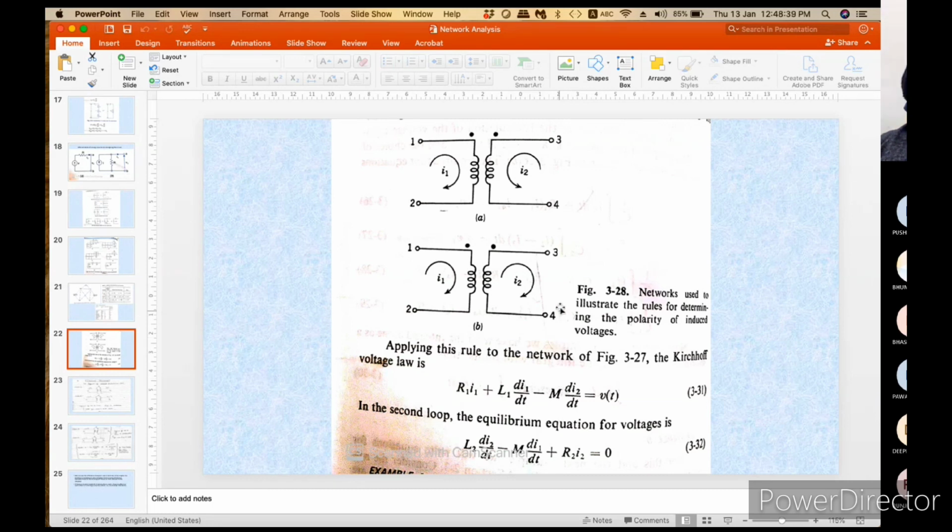And therefore, if these, for example, two dots are on just one side, for example over here, the directions are different over here. The current is flowing in this direction and in this direction, and these dots are shown to indicate that the inductance at that time is getting transferred from this to this, okay. And therefore, because you also have to consider the direction of current, the direction of current is opposite over here, and therefore though this is on the same side, okay, still the mutual inductance will be negative.